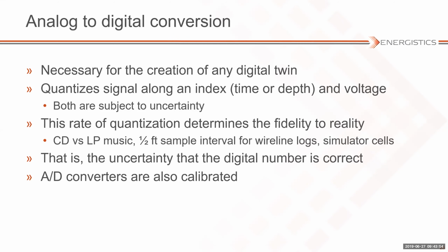It's calibrating both the analog device and the incorporated A to D converter, but sometimes in the field you'll find that those are separate pieces of equipment and they need to be calibrated separately. But it's more data to manage. The maintenance activity of doing those calibrations is what knowledge workers need to know if they are doing something that requires high accuracy data to feed some computation.